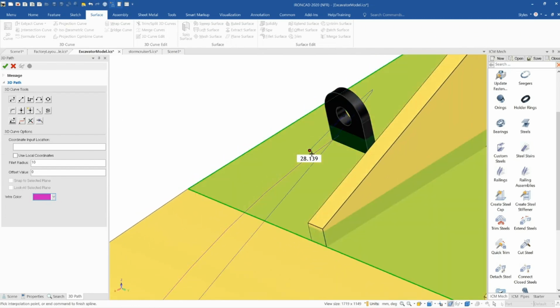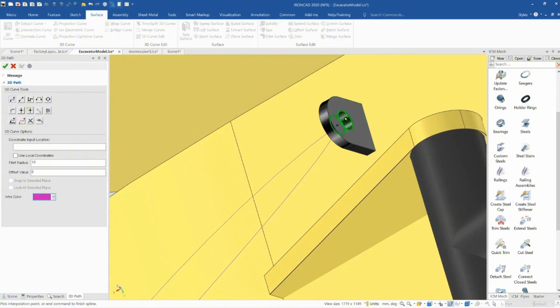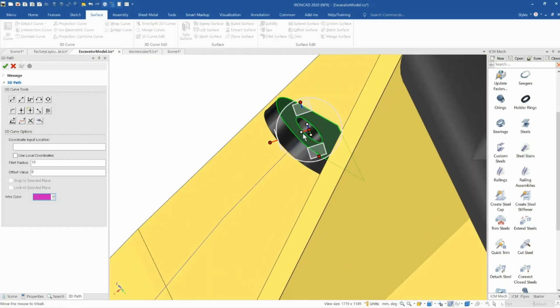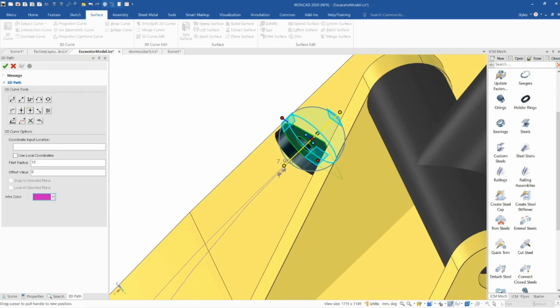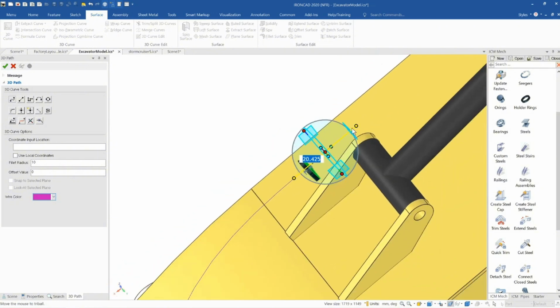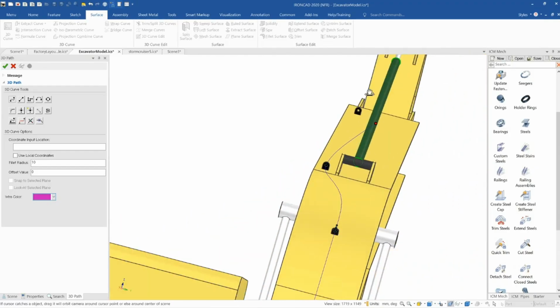And the dimension's just in the way a little bit there. If we just click into that, it should go away in a second when we rotate. And I'll click on this next point here. And again, activate the tri-ball, move it into position, and then align it where we want it to be aligned. So I'm going to drag that to there after hitting the space bar. And now again, I'm just going to drag it, P key on my keyboard a few times, and then deactivate the tri-ball with the Q key or F10 key, and then drive across to the next piece here.